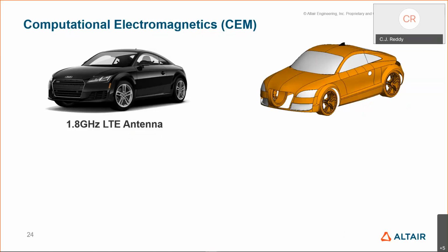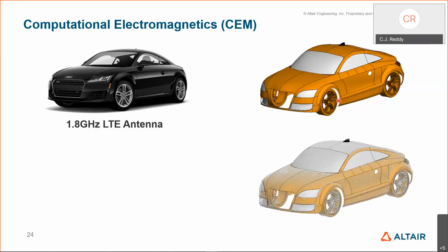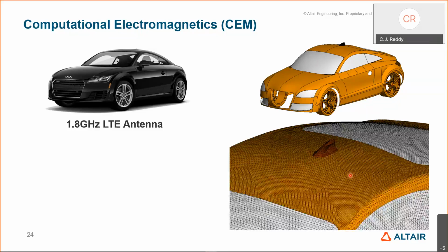So what numerical methods do is take that CAD geometry and discretize it into what we call a mesh or discretization. In this case, we are discretizing this with triangular elements. Essentially, we are splitting this complex shape into very known small triangles.